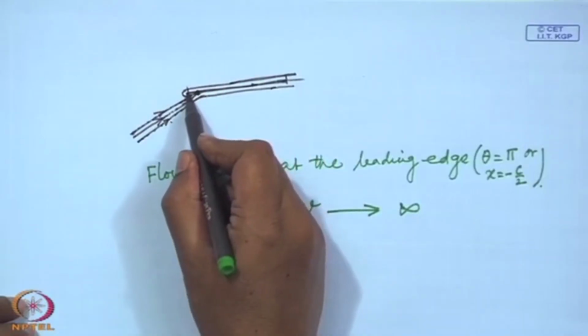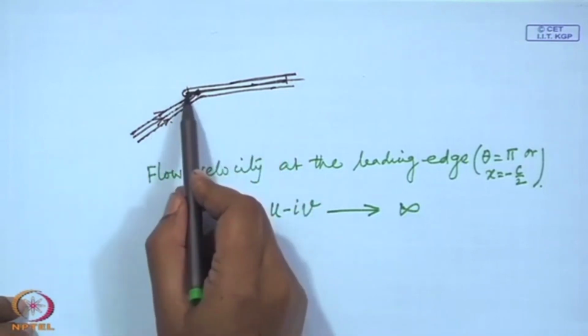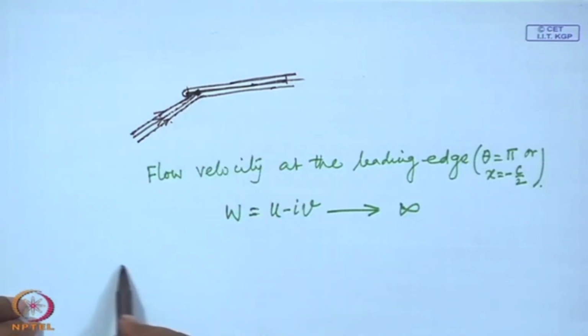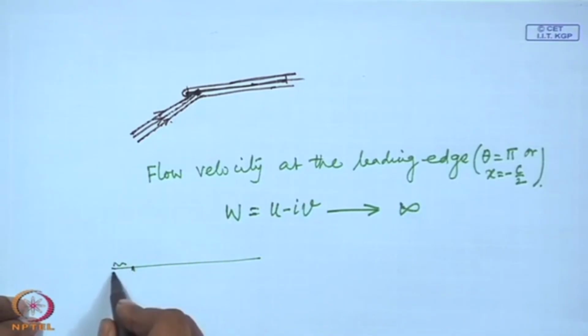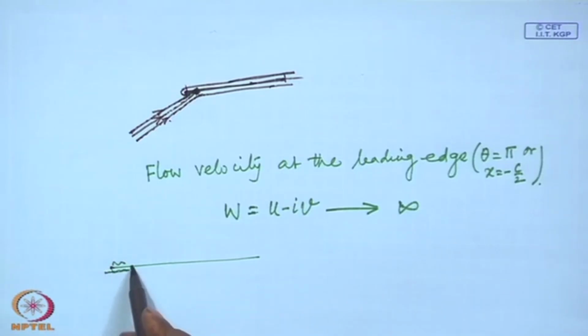But in this inviscid flow, if you look at this figure, at this point, which is the stagnation point, as we move to this side, which is part of the upper surface, the front part of this flat plate, which is ahead of the stagnation point, and this part on the lower surface, flow velocity is increasing from 0 to something. Here it is becoming undefined. You are calling it infinite in the sense that it is going on increasing, the flow velocity here is 0 and then gradually increasing, and here it is undefined, you are saying very large, because it was very large ahead of it.